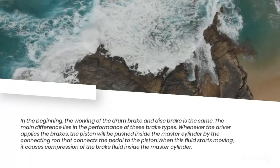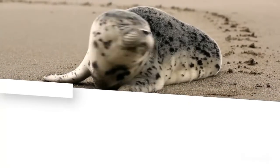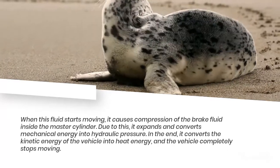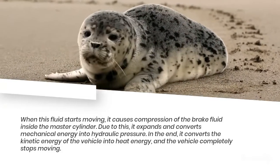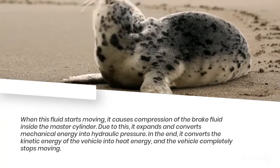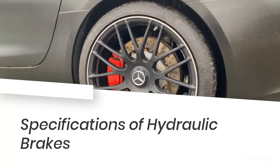When this fluid starts moving, it causes compression of the brake fluid inside the master cylinder. Due to this, it expands and converts mechanical energy into hydraulic pressure. In the end, it converts the kinetic energy of the vehicle into heat energy, and the vehicle completely stops moving.